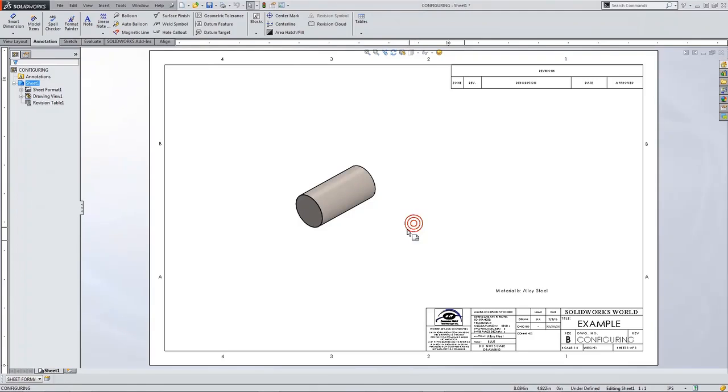So if you're on a network, you would have to check that after moving it to the network or verify that? I would have saved the sheet format directly to the network in that location. And it should, if you've got your file locations set up pointing only to that, it should take you there anyway, so you don't have to really browse to it. If you have more than one, and I think you can have more than one for sheet formats, maybe not. If it's the first one, then it might not be the right one, so you might have to put it in the right spot.